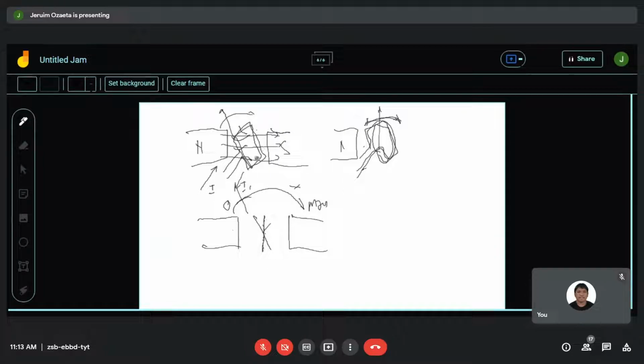Now, what makes the proportion out of this instrument? If we connect a spring around here and we suspend the spring, meaning spring na ito, this spring is going to resist the magnetic force that is induced by the current in the coil under the influence of the permanent magnet.